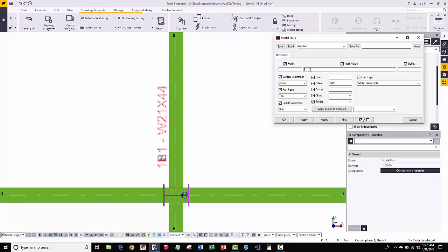Right now I've got, for instance, part position in there, and then you basically close the template editor value with brackets, and then you can put a space and then a dash, and then we have the profile in there. So let's just say profile, and we'll keep that, but then let's also do another one here, and let's just put in material for an example. If you put in material grade and you just say modify, you can see here that it puts in all three of those properties.